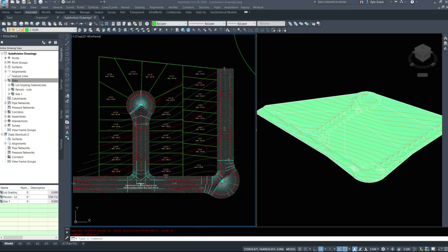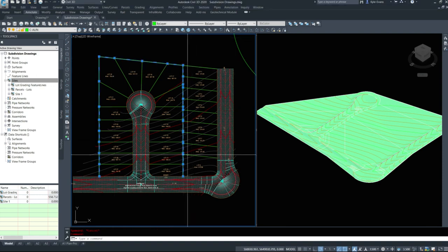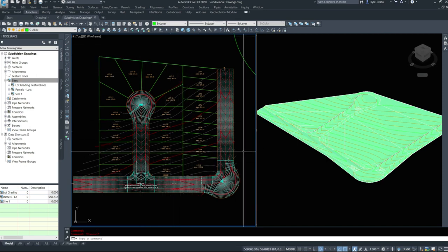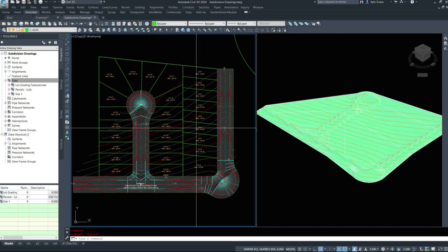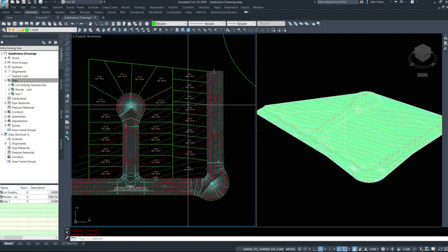All right, all my lots have been traced with a simple polyline. I've gone around the backs as well, the backs of all the lots. It makes this one easier because these two share a slope, so we'll have to work together to make these lots work. And I'm going to guess some of these will be maybe a split lot configuration, some of these will be back to front, etc. But I've traced every single lot line.